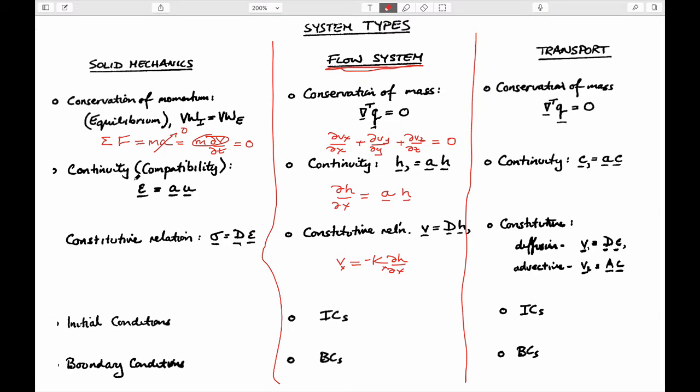The continuity equation is that displacements are continuous, and so they have to satisfy the fact that displacement gradients, du/dx, is equal to a ux, if you like. And so this is a gradient, and it just comes from a transformation of nodal displacements. And this is Hooke's law, nothing more.